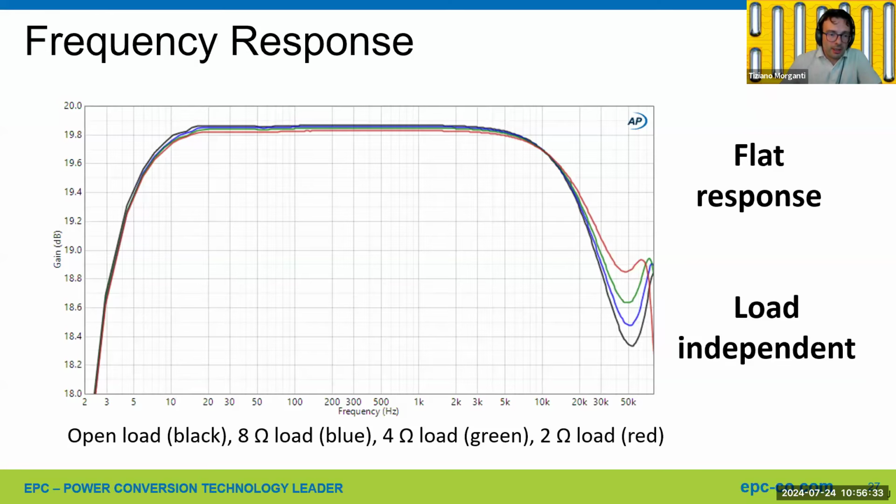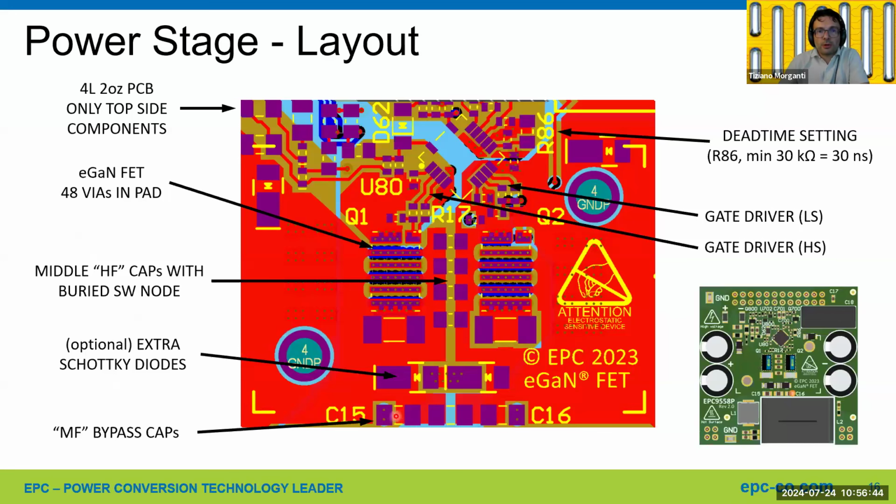Then we have, let me show you the slide with the layout, this one. So then we have those mid-frequency capacitors. So we have 100 nanofarad, 200 volt between the plus and minus VCC. And we have a 1 microfarad, 100 volt from ground to the rail. And those are dropping significantly. Maybe we have an effective, an actual 300-400 nanofarad capacitance between rail and ground.